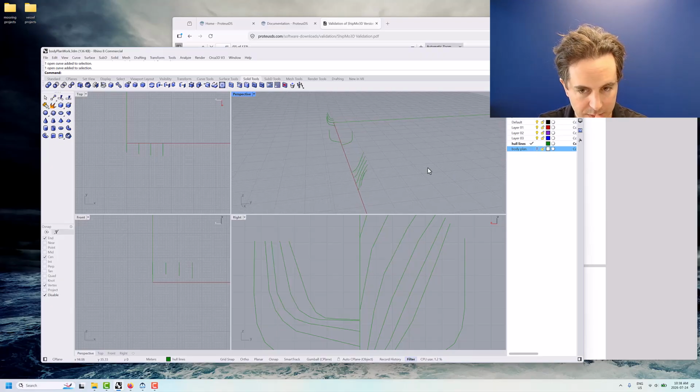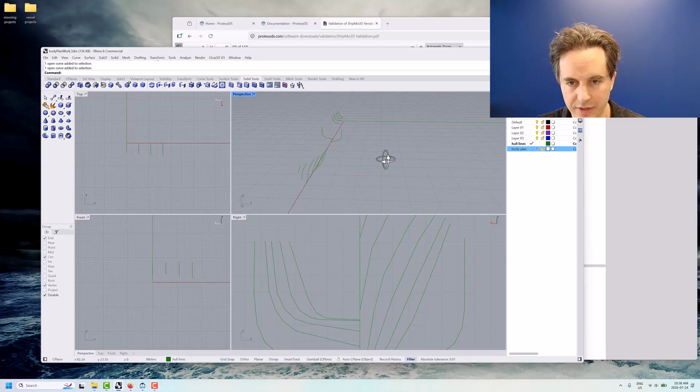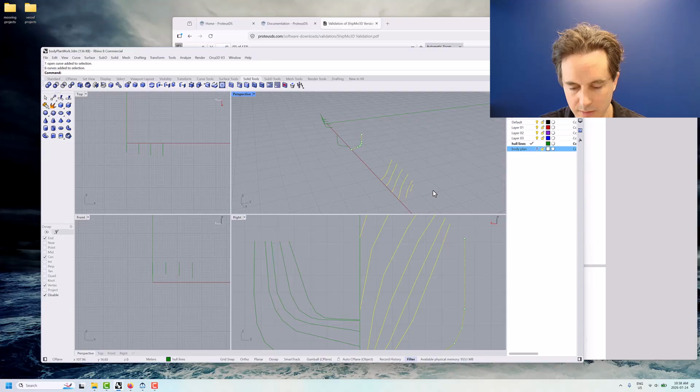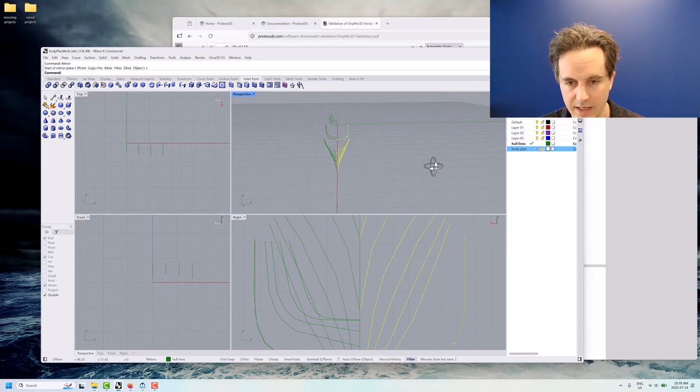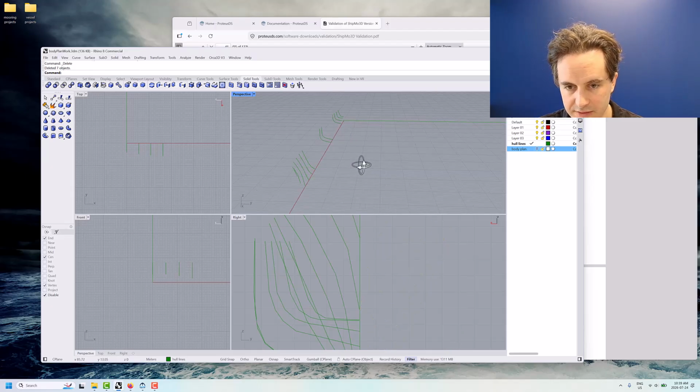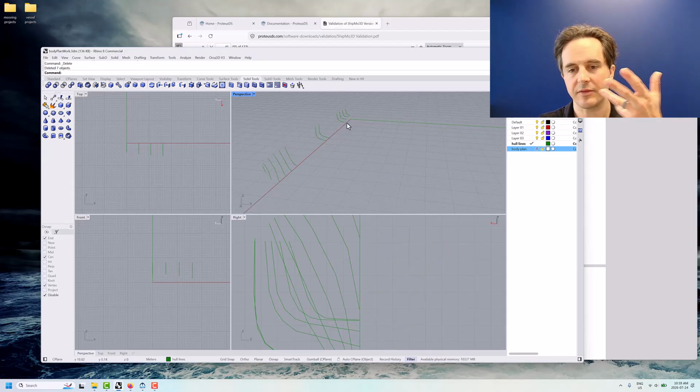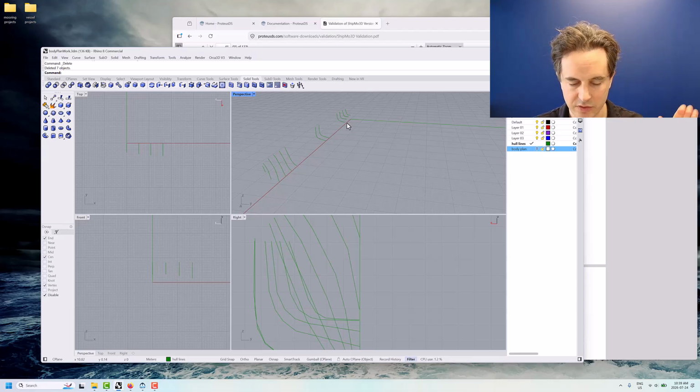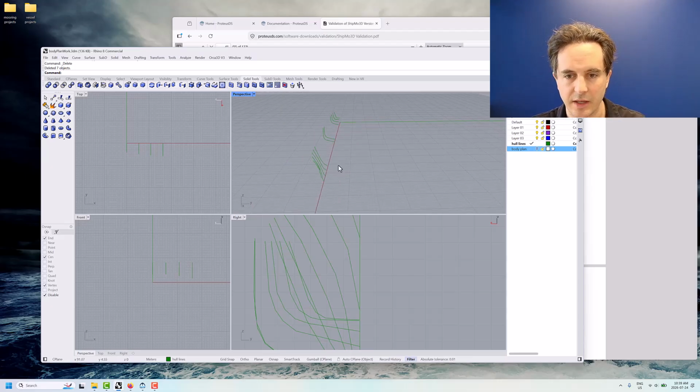So now at this point, there's a couple things we want to do. First, we want to get all the lines on one side. So that's pretty easy to do. I'm just going to select the line there and hold down shift and select the rest of them. And we're going to go mirror. And we're just going to pick the x-axis. And it's mirrored the lines, maintaining selection on the remaining ones. Now we delete those old lines. So we need to have all the lines on one side because we're going to do the sweep command through everything. Now, maybe it's a good time to save the project.